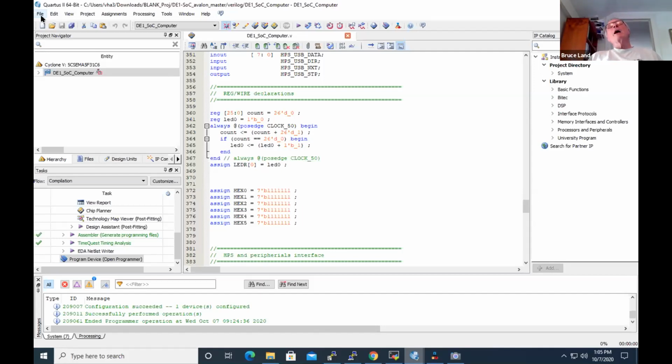So if you feed back 1/10 of the output frequency, then the overall phase lock loop multiplies the input frequency by 10. So it is a frequency multiplier. There's no other way to do it that I know of.